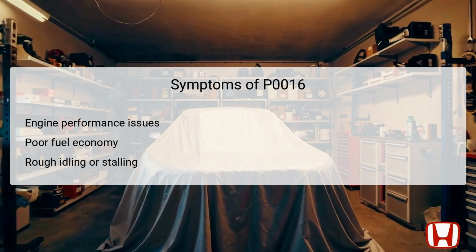Drivers might also experience rough idling or even engine stalling, especially at low RPMs. Additionally, the vehicle may exhibit increased emissions due to incomplete combustion as the timing is not optimal. Thus, addressing DTC P0016 is vital to restoring proper vehicle performance and ensuring compliance with emission standards.